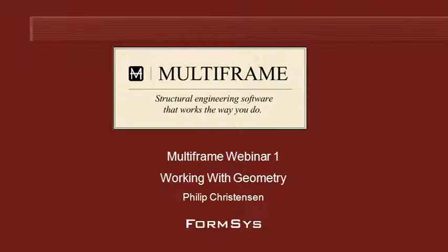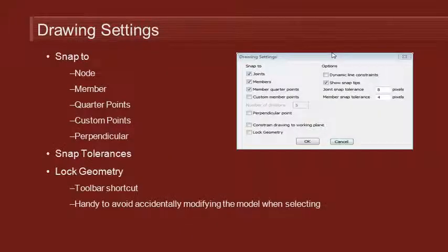Before we start sketching, we should use the drawing settings command to set up our snaps for interactive sketching. So we can snap to a node or joint, snap to a member, snap to quarter points along a member, or we can snap to custom points or perpendicular points along any member in the structure. We can also set up the snap tolerances so that snap works smoothly whether on a large or a small